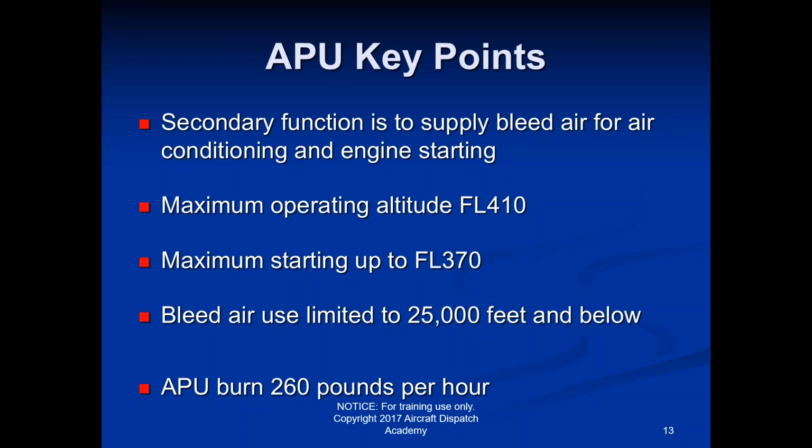Now, in situations that you've probably seen, where we accidentally send a plane that has no APU or an inoperative APU to a station that doesn't have an air cart, which happens more often than not. The coordinators are always supposed to call ahead, if a plane is routed to five different airports for the day, to make sure they have a working air start before we send a plane there. But sometimes the air starts stop working when they get there. I mean, there's a lot of different things that happen, but if it goes to an airport that does not have an air start,